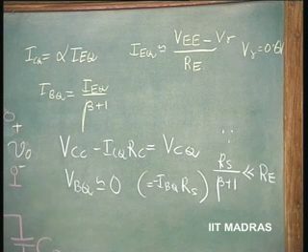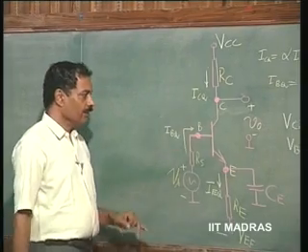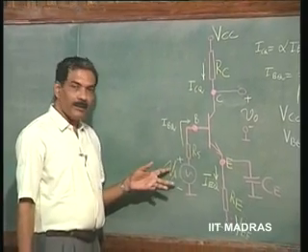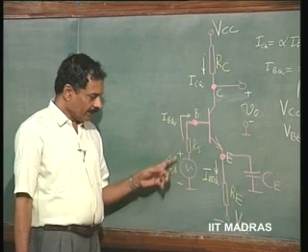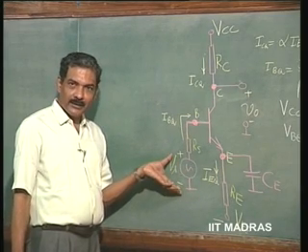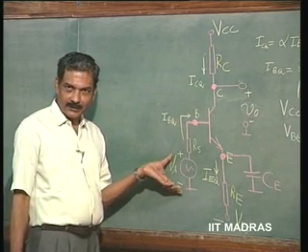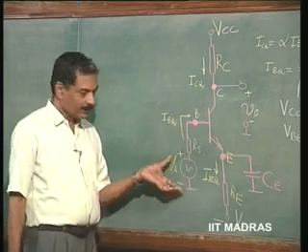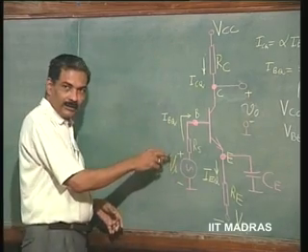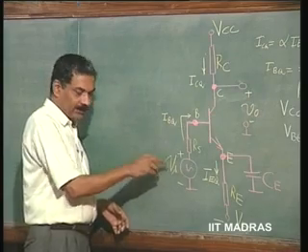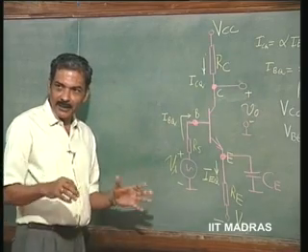So, this is a proper way of biasing a common emitter amplifier circuit. This is what we had discussed so far. Now, let us superimpose over this. Because of Vs, there will be a change in current. Let us say it is plus here minus here, indicating that the voltage is increasing, delta Vs is positive here. Please remember, small letters with small suffix indicate the time variation in signal.